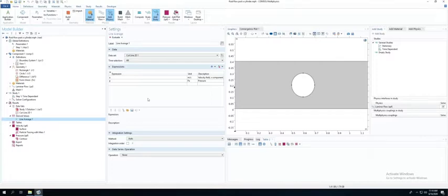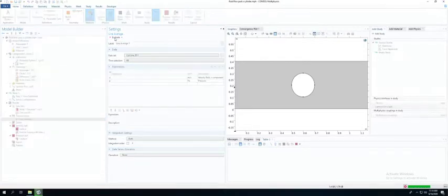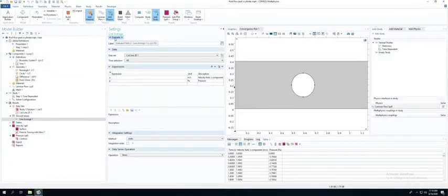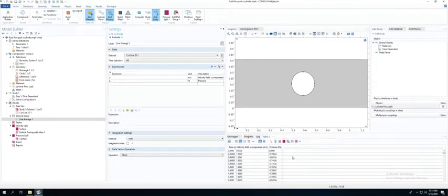All right. So now that I have that in there, and I'm grabbing the data points on the cut line, I can just click evaluate. This might take a second. And now you can see a table is generated down here in my message board. And this is all my velocity field measurements for the X direction, which is where our fluid is flowing, so we wanted to grab that. And the pressure.